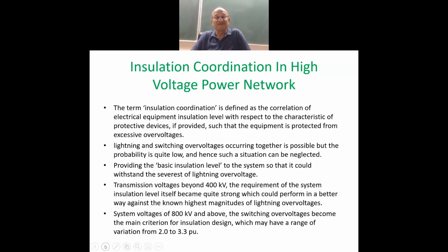So that is how a system of insulation developed, and that system is called insulation coordination in the high voltage power network. The term insulation coordination is defined, mind it, very important. I'll read it out for you and explain: the correlation of electrical equipment insulation level with respect to the characteristic of protective devices, if provided.